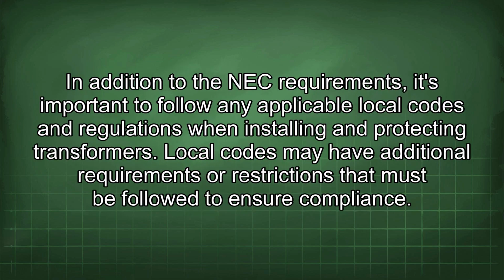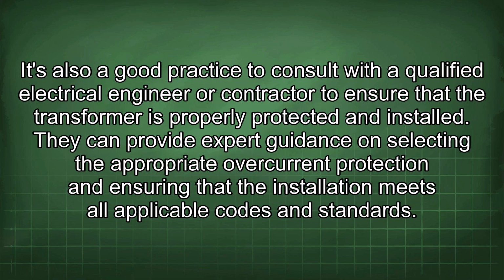The size of the overcurrent protection should be based on the transformer's nameplate rating and the recommendations of the manufacturer. In addition to the NEC requirements, it's important to follow any applicable local codes and regulations when installing and protecting transformers. Local codes may have additional requirements or restrictions that must be followed to ensure compliance. It's also a good practice to consult with a qualified electrical engineer or contractor to ensure that the transformer is properly protected and installed. They can provide expert guidance on selecting the appropriate overcurrent protection and ensuring that the installation meets all applicable codes and standards.